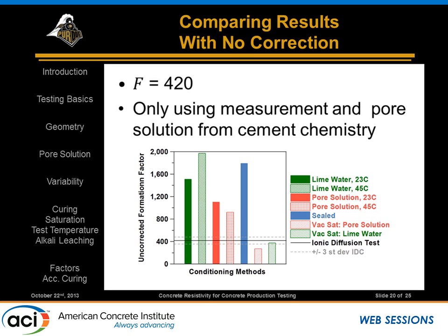So the nice thing is with the sealed sample, you just have to correct for the degree of saturation, but the degree of saturation should be something that you could easily measure if you needed to, and should stay relatively consistent through the different mixtures. And then you can also take the cylinder out if you want to break it or you want to do any other wild exotic thing to the cylinder, you've got it.